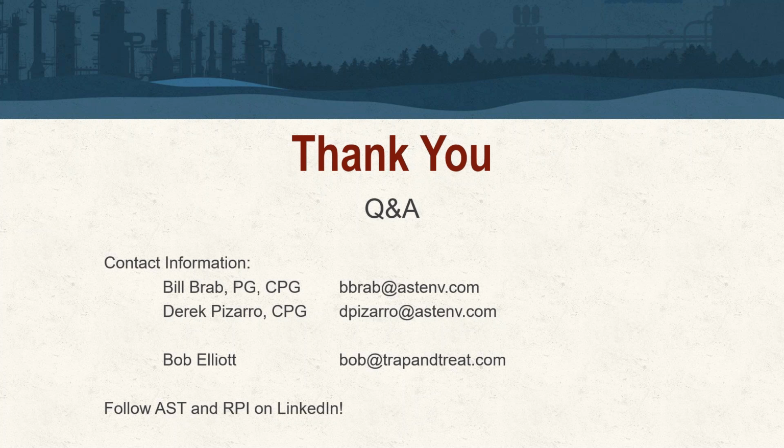What is the max flow rate in GPM of the triplex pump? 300 gallons per minute. How about max pressure? Max pressure is around 2,500 psi. Just to reiterate that, the pressure we deal with is mainly to get through the system and to initiate breakdown of the formation. So most of what we see from injecting does not reach that upper limit.